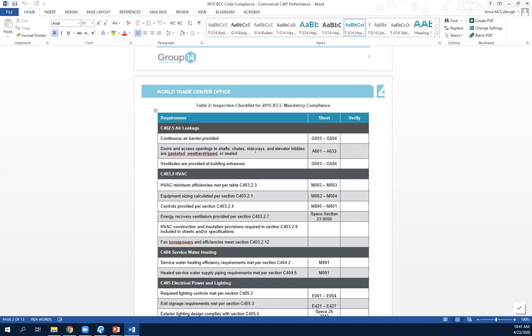And so for all you code officials on there, if you're in climate zone 2 and you're sitting there looking at your code book and you're like, oh, I can't let you put in more efficient equipment in lieu of an economizer because look, it's 2A or B, whichever it was. But anyway, they fixed that in the 18, just so everyone knows.